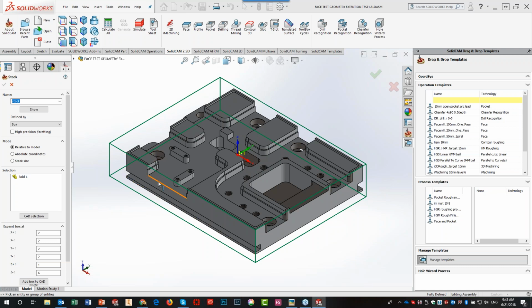Okay, I've created my stock over here, and I've told it I wanted offset extended by 2 millimeters on each side, but I don't know what my actual stock size is. And if I start measuring this afterwards, that doesn't mean that's the actual stock that I have available to me. So I may go back and see into my stock room and see my stock is not really that exact size. Then I would actually have to start calculating, okay, how much do I need over here to add on? So it would actually not be the proper way to do it.